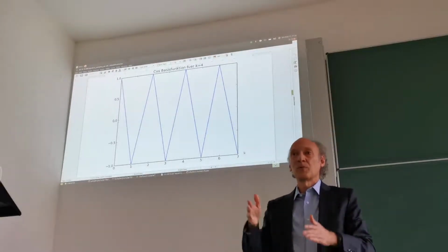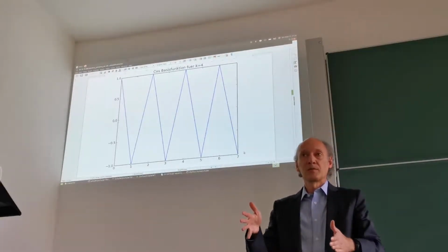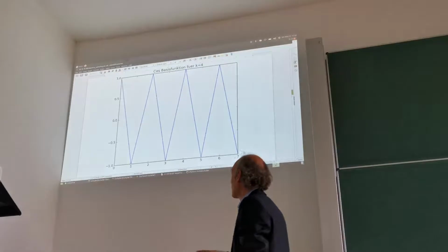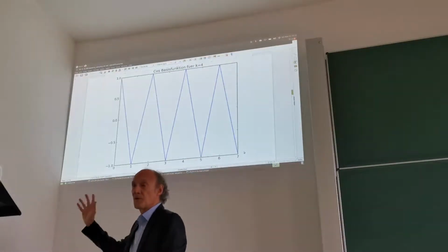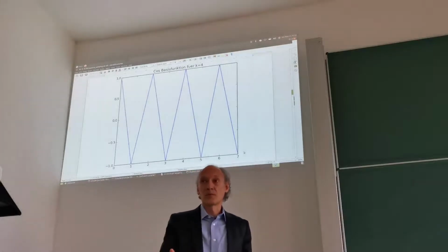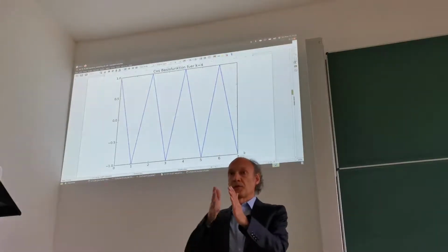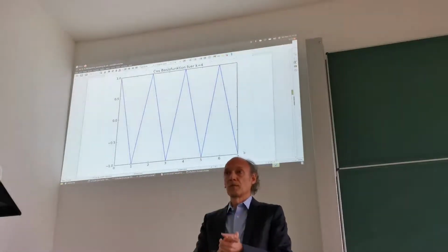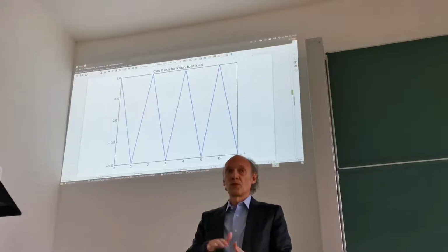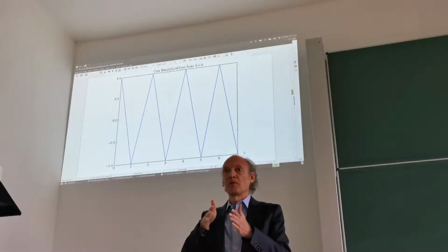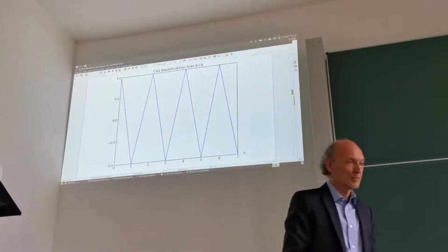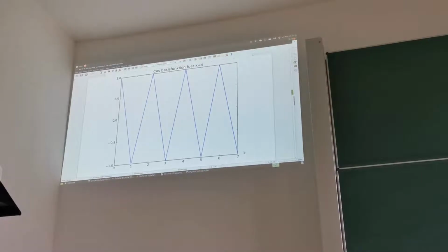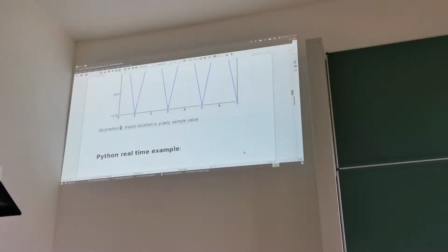So this is basically part of sampling. The maximum rate of change we can get with a given sampling rate is Nyquist, where we have one sample plus, the next sample minus, and so on. If you try to do this faster, then in effect we go down in frequency. That's part of the symmetry that we observed.